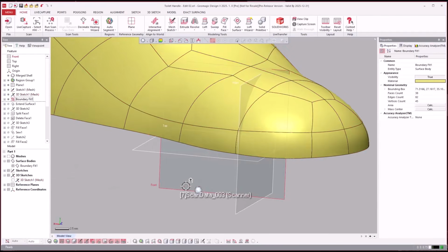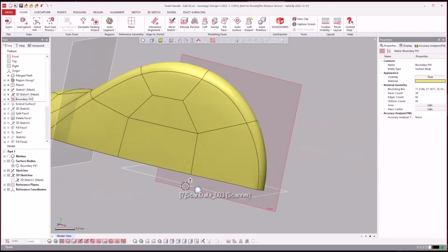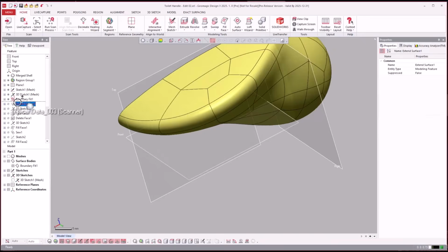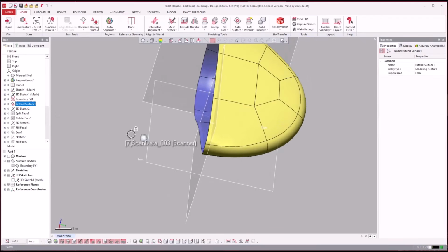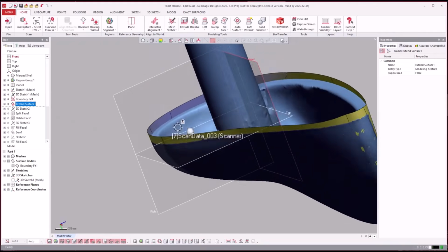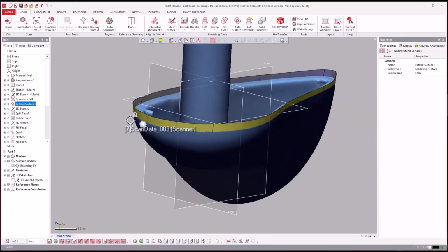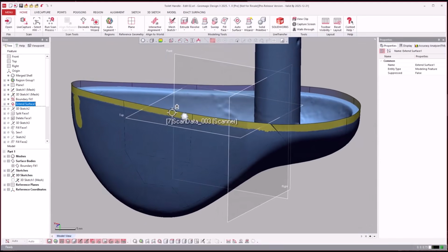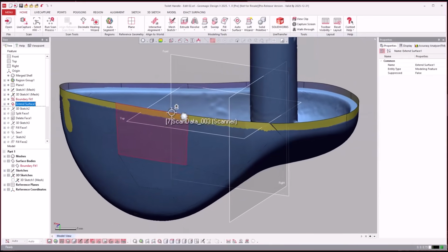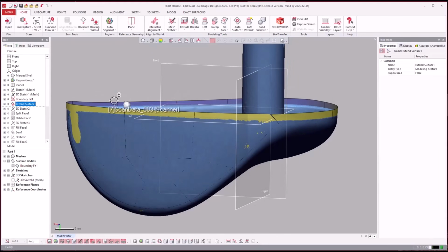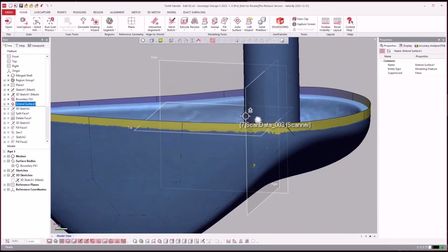And we will turn this off. So look at that. That's a beautiful surface that it extracts from that surface there. And then what we did is we extended that, because you see here we drew it where it was trimmed back, and then after we fit the surface, now we extended it. If you have nice clean surfaces, you will have a nice easy extend. Now I could also just extend it by offsetting a plane, convert entities, and create a lofted surface between the edge of that and this, but we just did an extend.